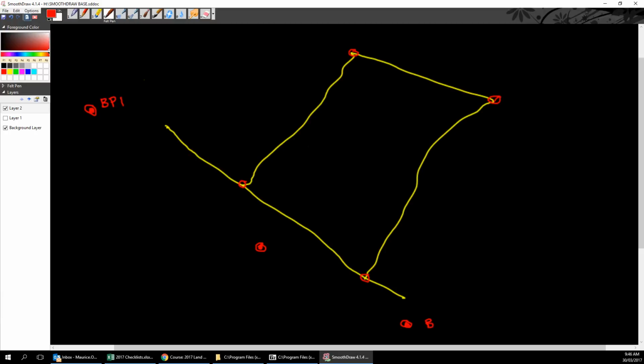So these come in various orders. So the brass plaques might be what we call survey standards in around the town, quite important marks. And then this might be just iron spike 1 here. That was put in on the line down between these. So typically these will, I'll show them as a dotted line.